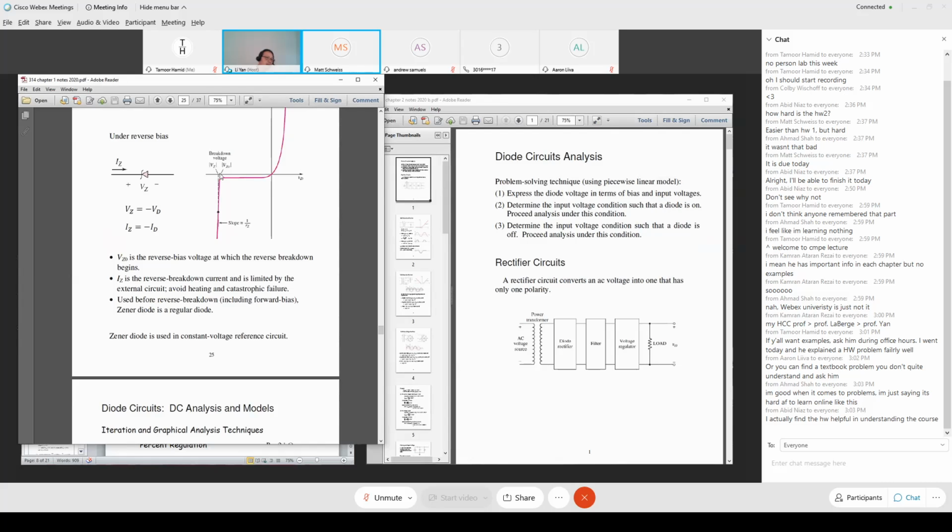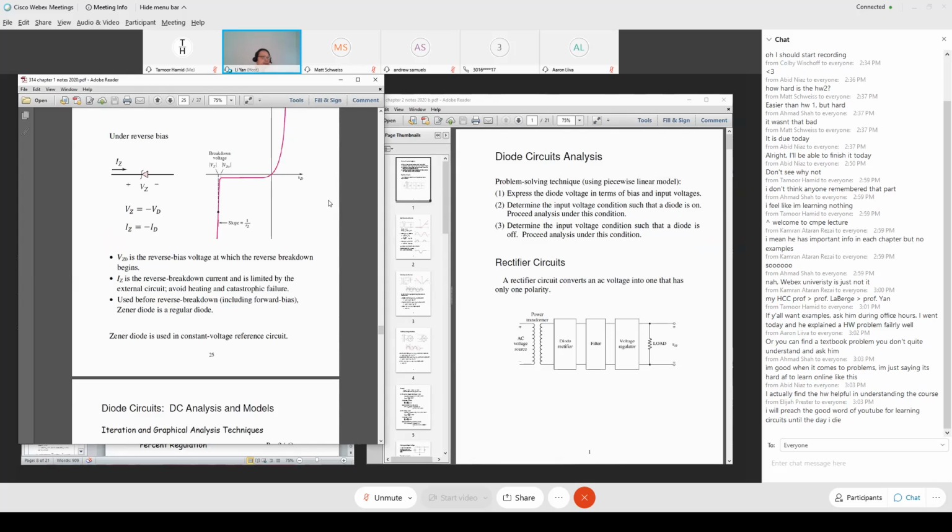And also that it's linear, because that is almost a straight line, but the equation that has e to the power and so on would tell us that that's slightly not, right? No. It is, which part? This is a straight line. It doesn't apply to this small corner. But we operate the Zener diode not near the turnaround point. We operate the Zener diode mostly in this region. That's a straight line.